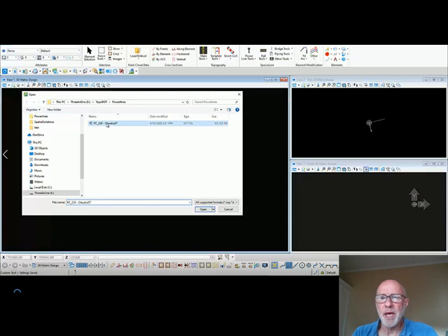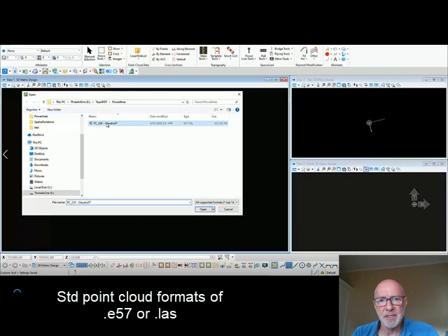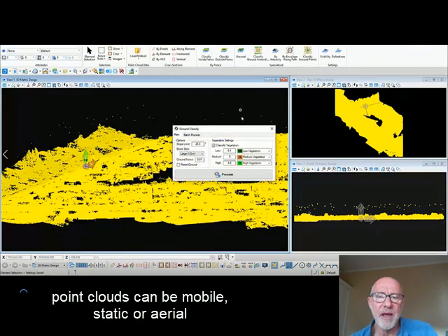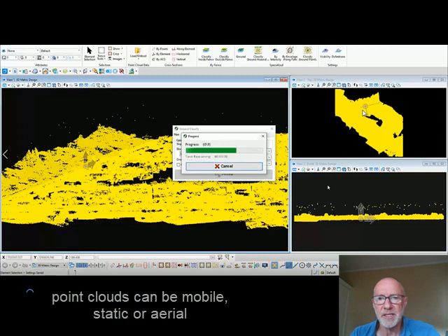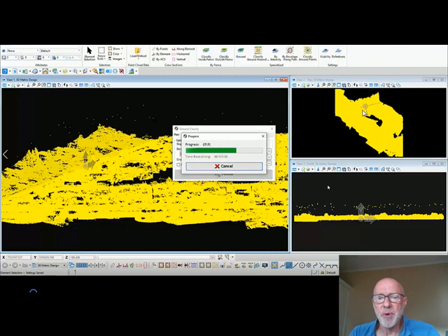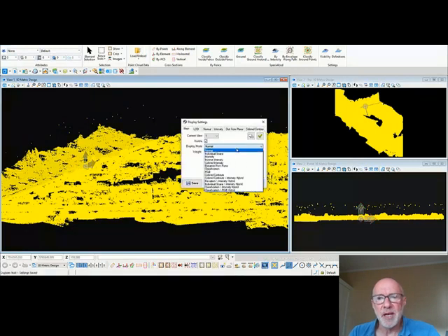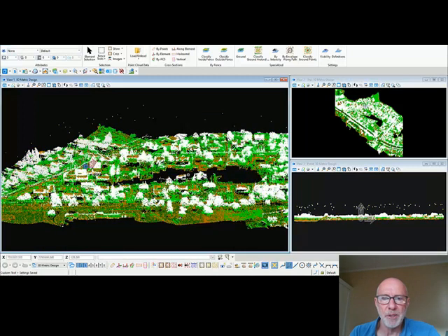In this video, we'll look at extracting power lines from a point cloud dataset. In this instance, it's an E57. When we load the E57 into the application, we then have the opportunity to classify the individual components within that dataset. This way, we're able to separate out the ground, low-level vegetation, high-level vegetation, etc. By turning on that classification, we can then differentiate between those individual components.